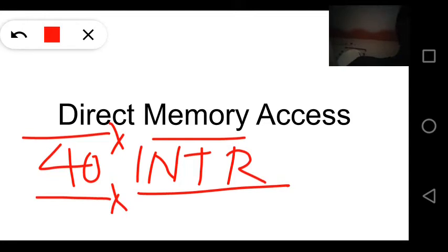all of you know that it has to complete the current instruction execution, load the content of the PC, that is the address of the next instruction, into some temporary buffer, save the status of the registers, and then execute an interrupt service routine. All this takes considerable time.